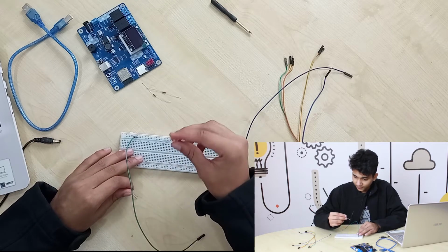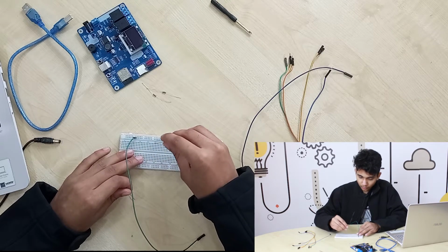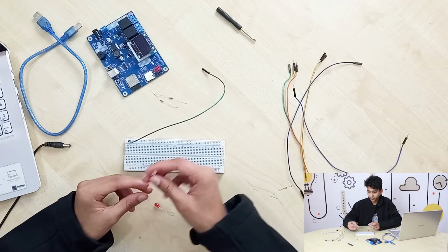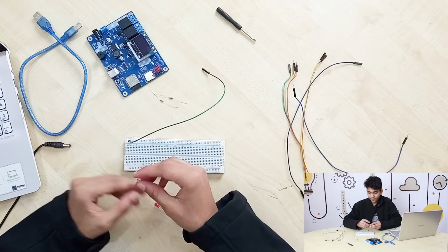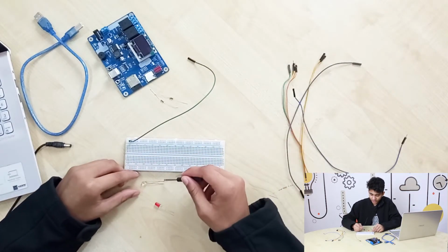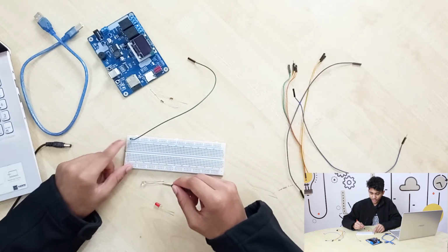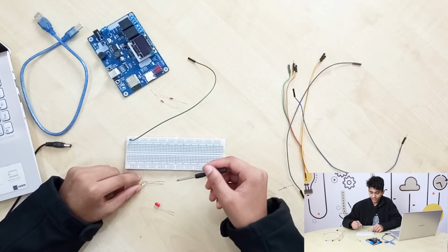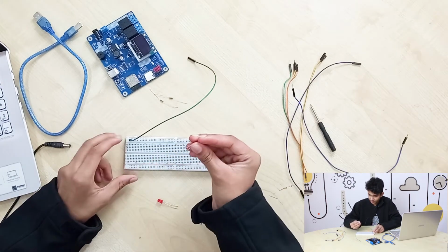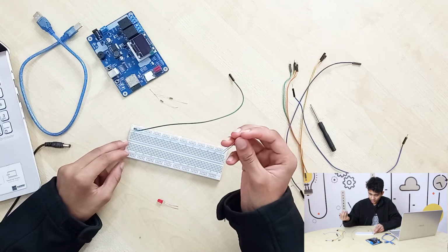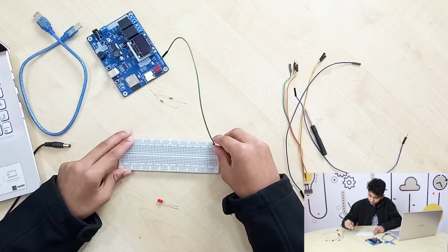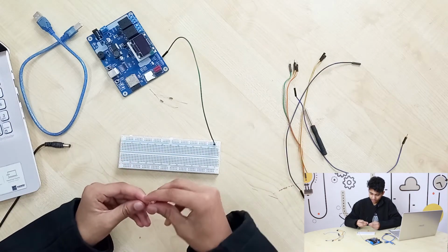Make sure you connect the right polarities because it's an LED. The long pin here is the anode and this one is the cathode. The cathode is negative and the anode is positive. So let's connect it using that. Okay, does look good here. Let's connect it here. It doesn't look that good. Okay, so let's connect our